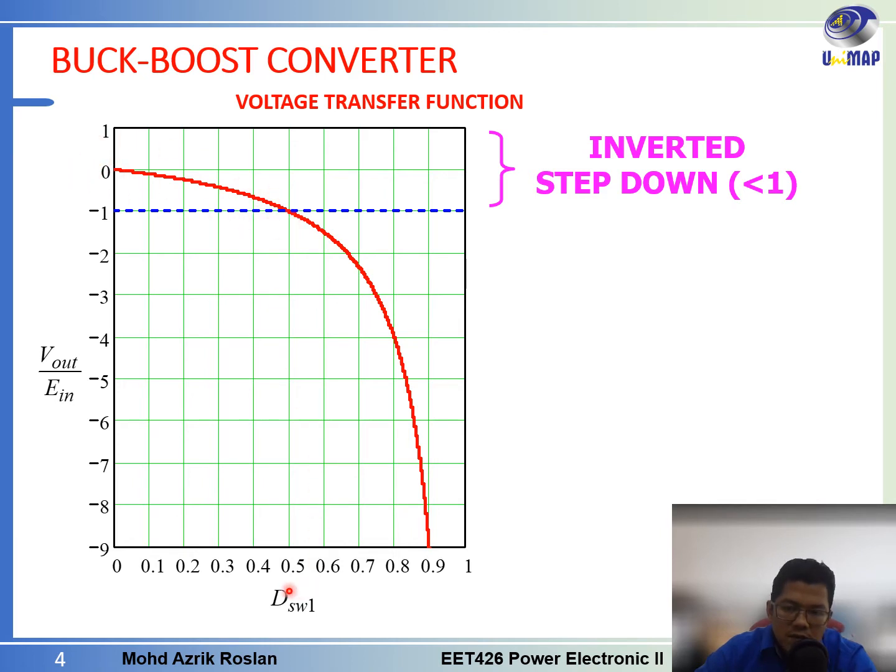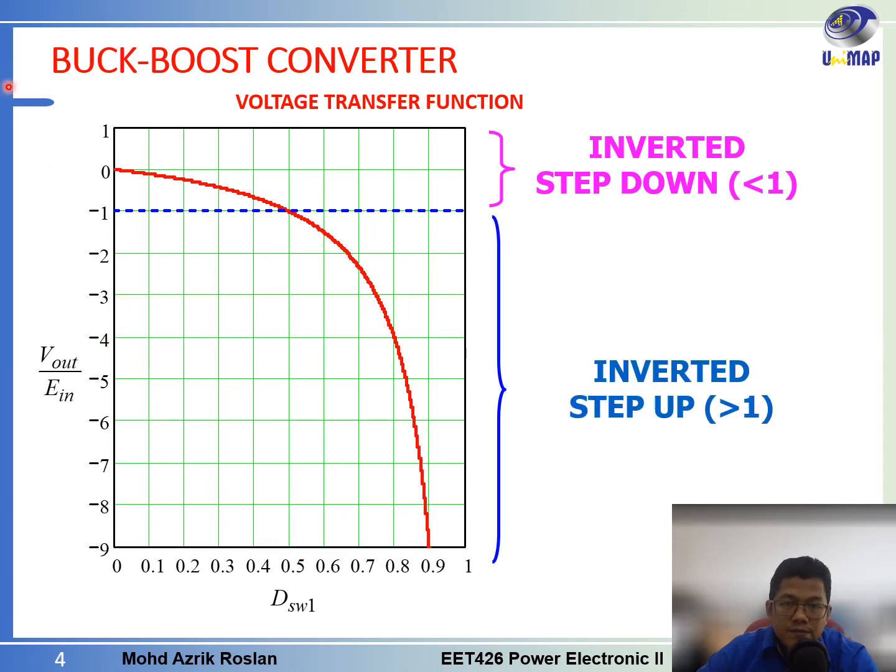Okay, but for the duty cycle more than 0.5, we can have the output voltage bigger than the input voltage. Okay, so this one is in boost mode. So we have the bigger magnitude at the output but reverse in polarity. So this is the step up side or boost side for this one.